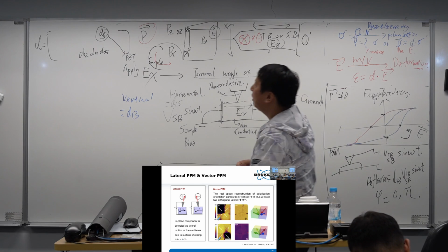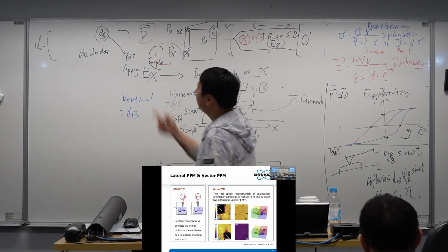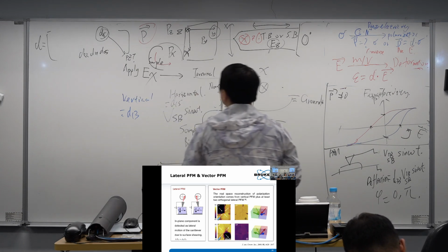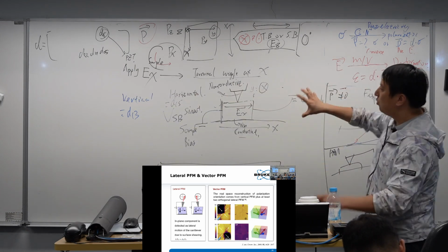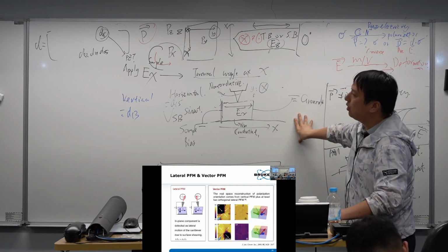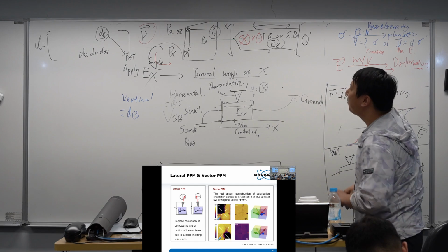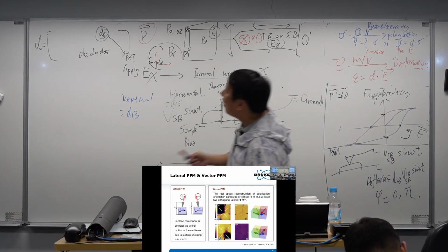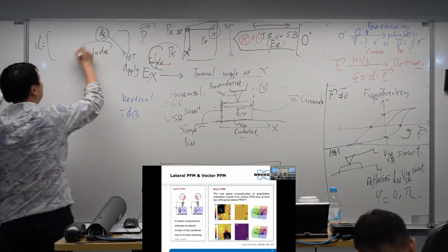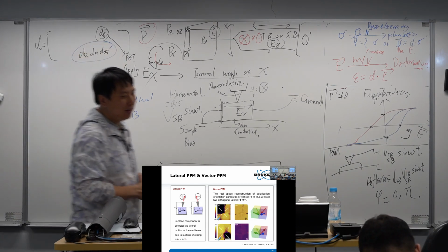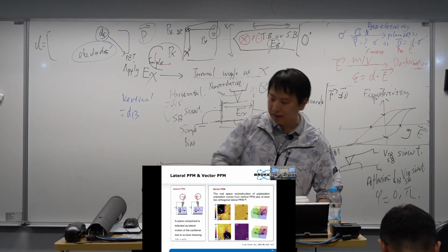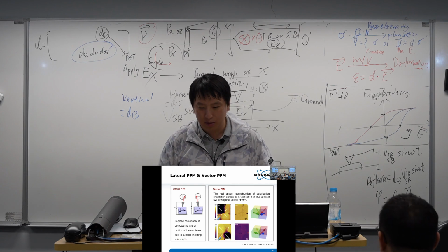But in the real setup, for the PZT, the D15 is important, the other things not so much. You can choose these kinds of setups based on your own crystal structures. But I have to say, nowadays we are focusing on 2D materials, where only these three are important. The others are not important anymore. Okay, so we keep going.